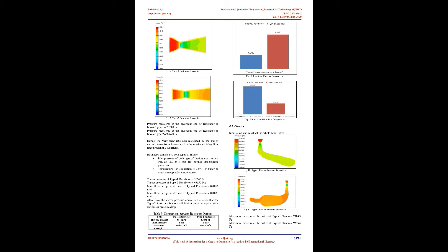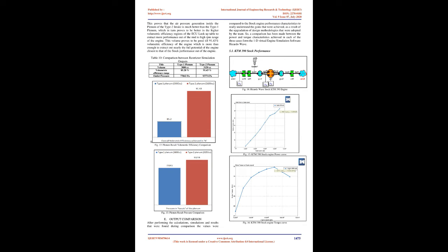3.4 Throttle body. So, in the Type 1 intake the stock throttle body was used upstream of the restrictor for ease of adaptability and sensor retainability. In the Type 2 intake the actual required size of the throttle body diameter was calculated to get a greater mass flow rate through the intake system, which increases the volumetric efficiency of the engine coupled to this intake. Also, restrictor saturation is at the near end of the band to use all of the restrictor potential.